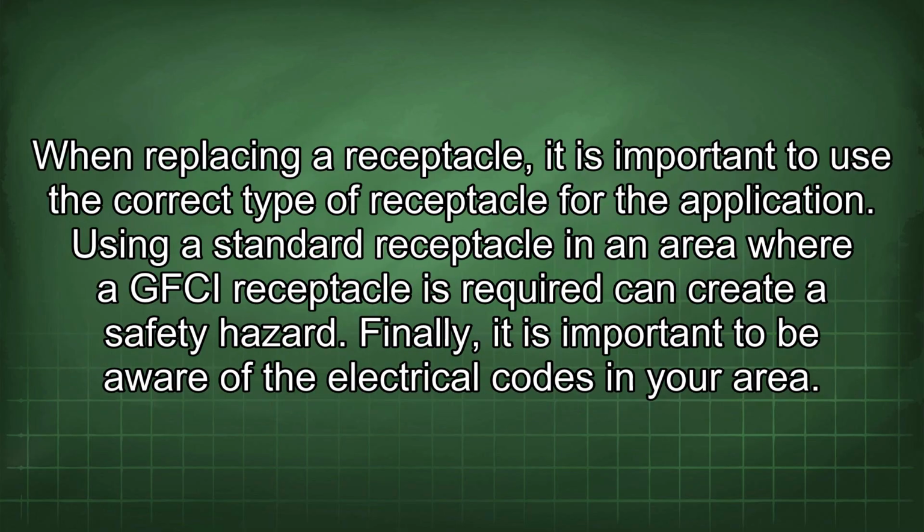When replacing a receptacle, it is important to use the correct type of receptacle for the application. Using a standard receptacle in an area where a GFCI receptacle is required can create a safety hazard.